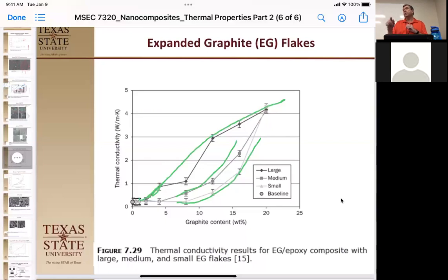Well, it does have a little bit to do with surface area, because that's your thermal interface with your matrix. But it's also, you would have to have two multi-walled carbon nanotubes crossing at some point, touching, to be able to transfer heat in two different directions. Does that answer your question? Yeah. Okay. So there has to be a low surface area to have that continuous. No, you actually want a high surface area because you want your matrix to have as much full contact with your device as possible.